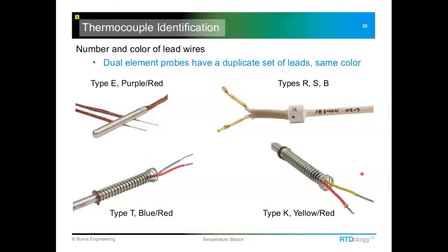Now, if you have one of the platinum rhodium thermocouples, this particular manufacturer labels them with a plus and minus to tell you which lead is which, because there's really not a good way to color code them, because platinum and platinum rhodium look identical when you just take a glance at them. The platinum rhodium one would be just slightly stiffer than the pure platinum one.